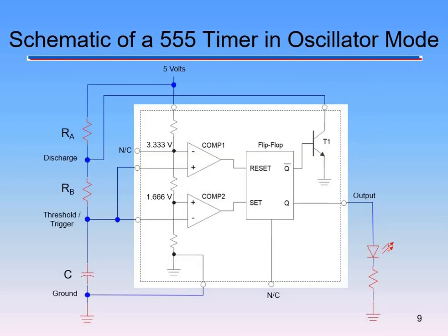All right, and here's what's really going on. The external resistance that we care about is the RA, the RB, and the C. Then we have an output on the LED that's just going to show our oscillation. Think about the flashing light on our breadboard companion. As we change the variable resistor, we can make that LED flash really fast or really slow. But what that's really doing is outputting our 5-volt square wave, and it's changing the frequency on our clock. This will all come together.